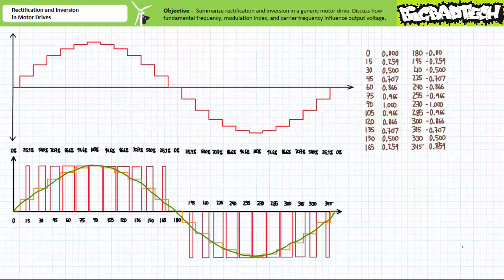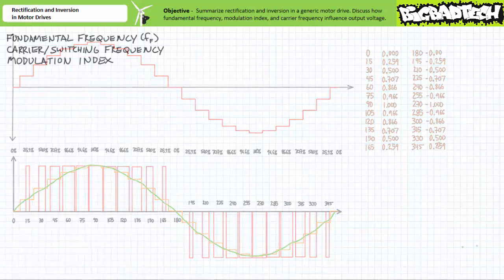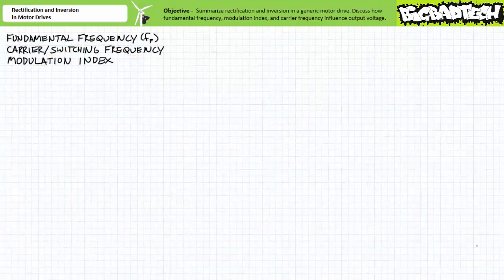The unfiltered output of the inverter is, as the name implies, modulated pulses of DC, where the duty cycle is varied to reflect the average values for an individual section. The filter then just smooths it out. A three-phase PWM inverter simply does this 3 times, such that three-phase AC waveforms have a respective phase shift of 120 degrees between each other. We'll examine both single-phase and three-phase AC pulse-width modulated inverters in greater detail in much later lectures on power electronics.